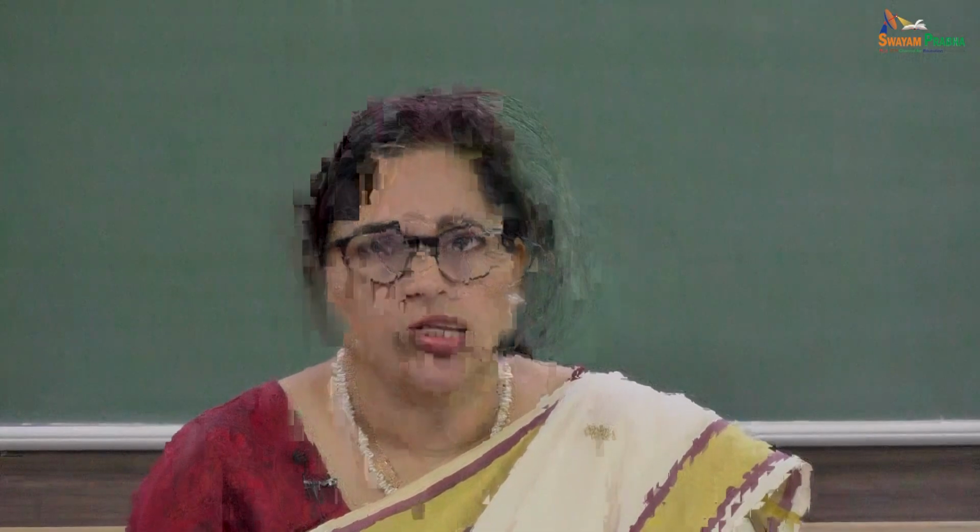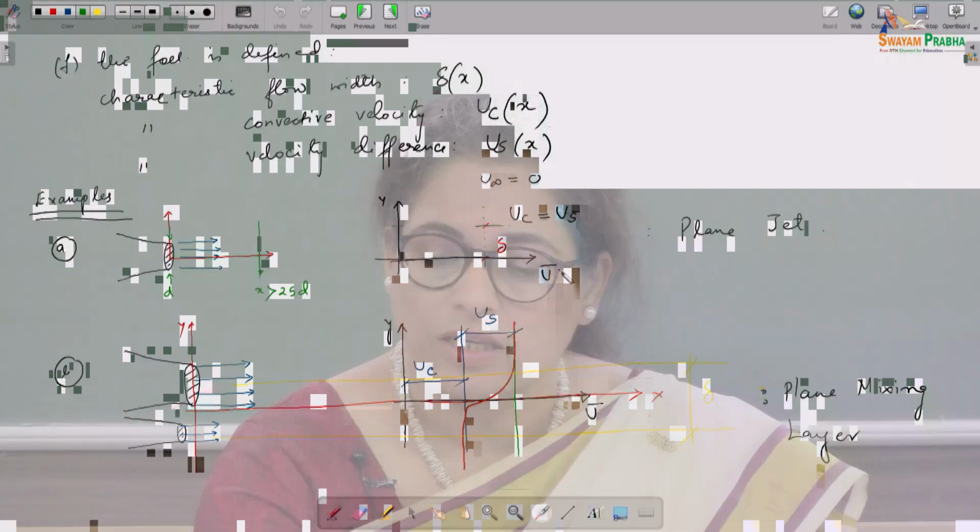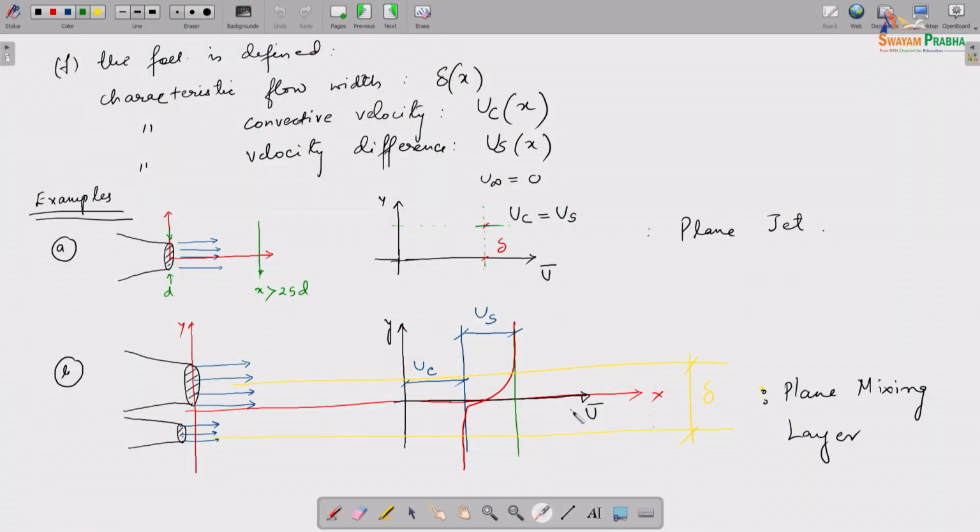Like I said, you could look up another course of mine, Introduction to Boundary Layers, where I have done that, or there must be other courses online as well as the standard textbook, Schlichting's textbook, and you can look at that. So I'm going to look at the boundary layer equations, which come from the Navier-Stokes equations, for these turbulent cases now. And when I do that, I'm going to use mean components of velocity, because I'm basically looking at the mean.